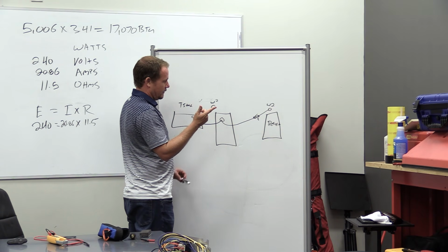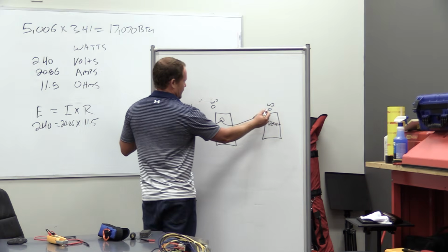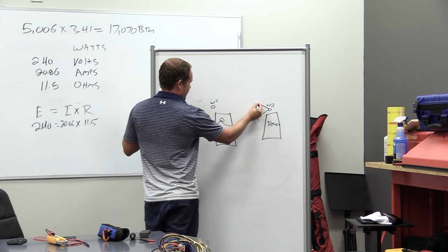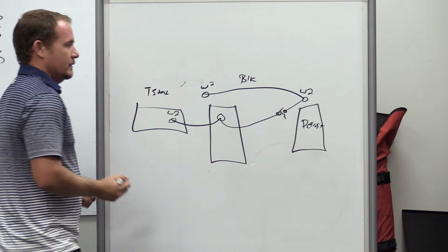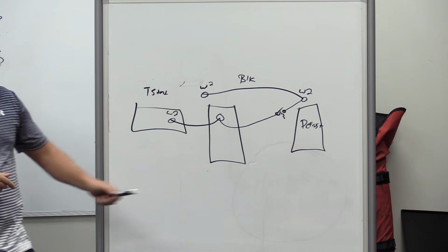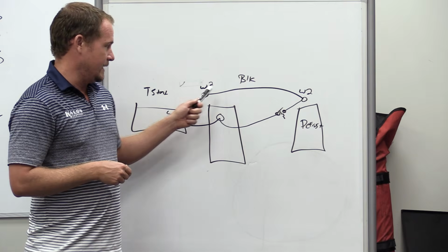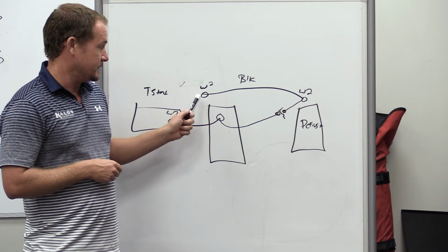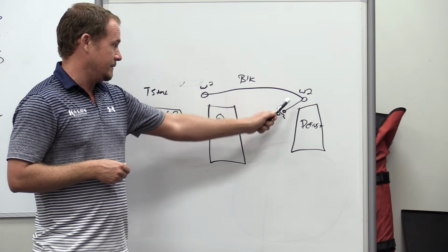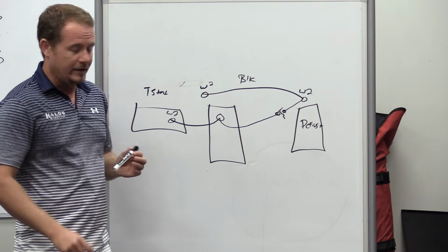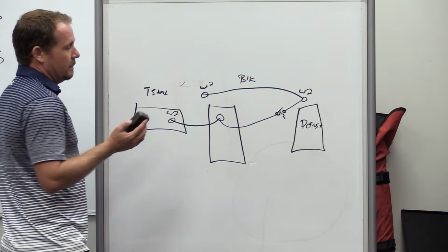into our defrost board, right? And then from here, we would run a different wire back, and this would probably be our black or brown, probably black if we have that extra. So our defrost board could still send a signal to bring on the heat strips by itself, even if this was open. But in order for the thermostat to do it, this has to be closed in order to send it back.